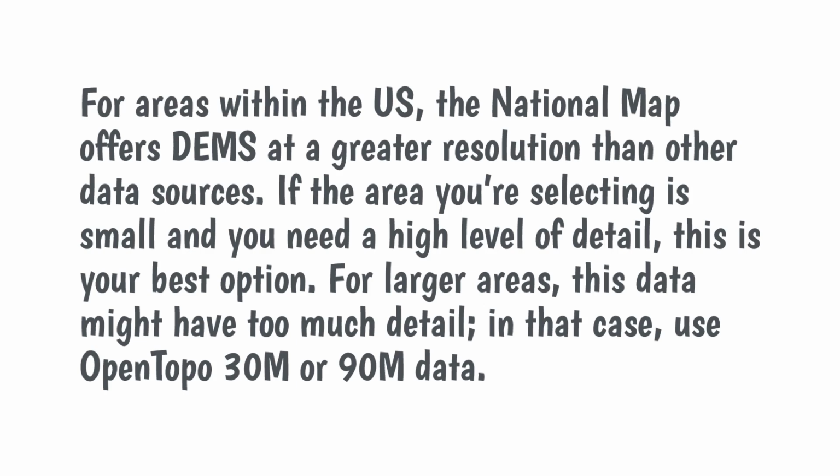For areas within the US, the National Map offers DEM files at a greater resolution than other data sources. If the area you're selecting is small and you need a high level of detail, this is your best option. For larger areas, this data might have too much detail. In that case, use Open Topography 30-meter or 90-meter data.